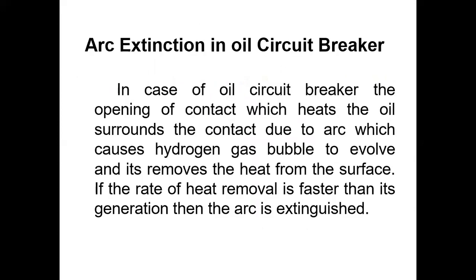The energy balance. Arc extinction in an oil circuit breaker. In case of an oil circuit breaker, on opening of the contacts, the oil surrounding the contact is heated due to the arc, which causes hydrogen gas bubbles to evolve, and it removes the heat from the surface. If the rate of heat removal is faster than its generation, then the arc is extinguished.